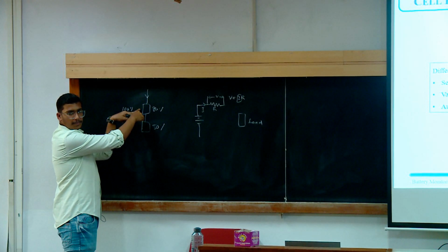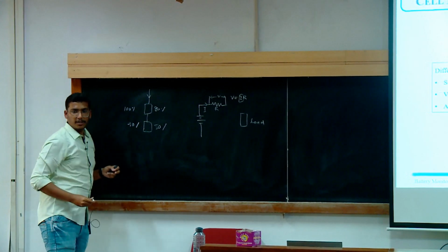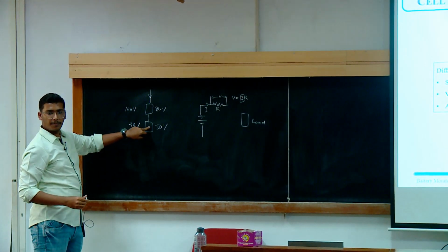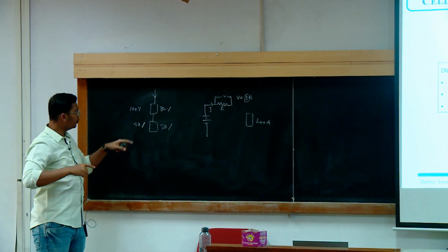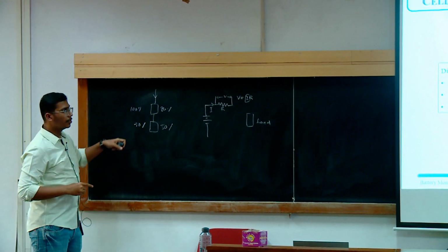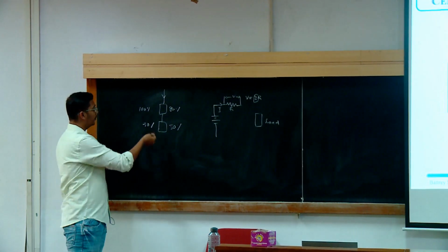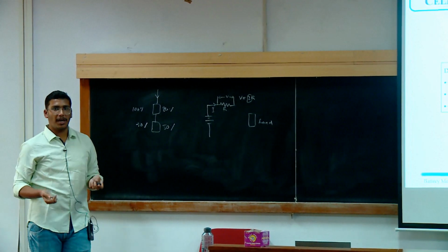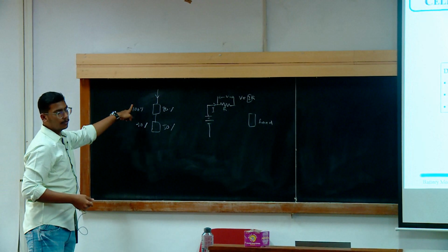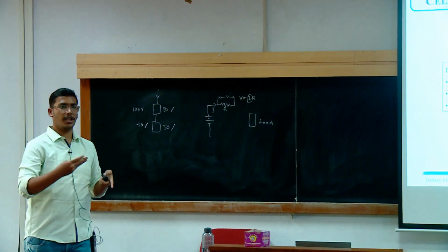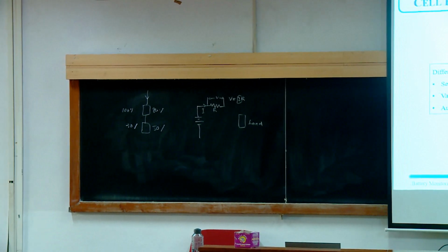So it has reached 100%, but how much has the other one reached? Only 70%. So this cell is undercharged, and it would give the command that you can charge me more, you can push more current through this cell. So if the algorithm is not fed properly, or if there are imbalances between the cells, the most charged cell in that string will get overcharged, beyond its capacity.